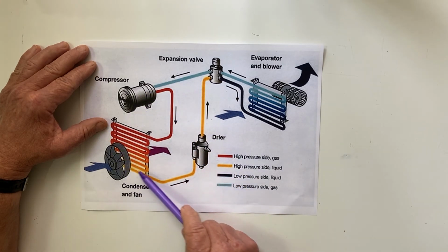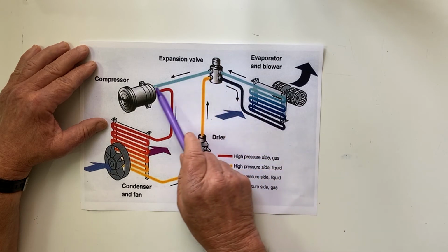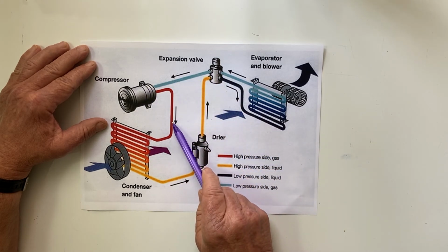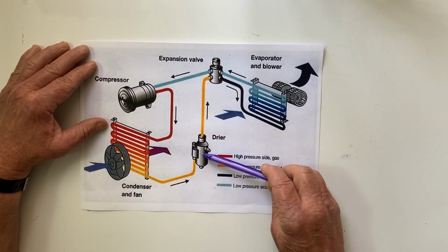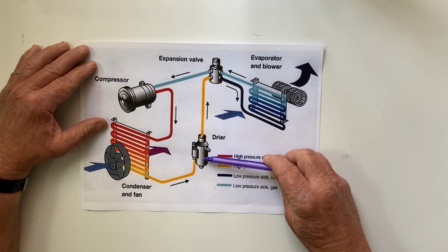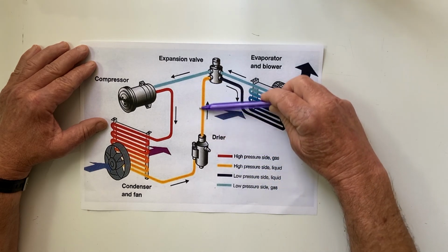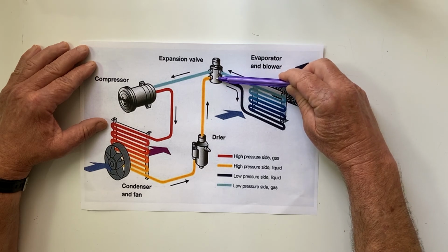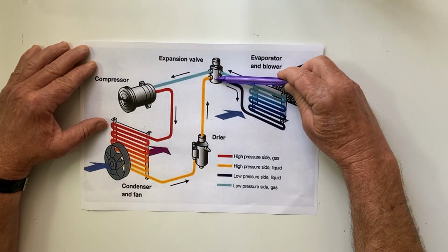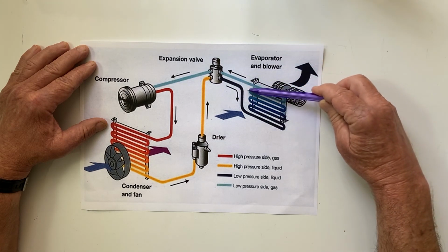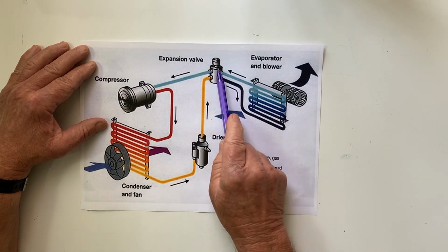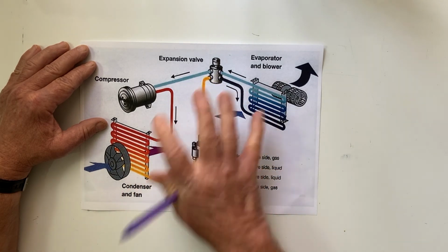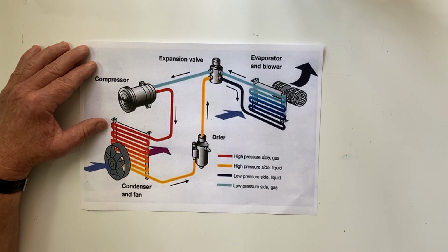So that whole cycle of the refrigerant is a continuous one. It goes in the compressor as a gas, comes out as a gas under high pressure and also high temperature, comes out the bottom of the condenser as a liquid, is filtered and also has any moisture removed, and makes its way up in the form of a liquid to the thermal expansion valve. That is where it changes from a liquid into a vapor, and that massive quantity of heat energy is what is used to cool down the inside of the machine. Then it returns back in through the compressor. So that's just a brief overview of the basic concept as to how the air conditioning system works.